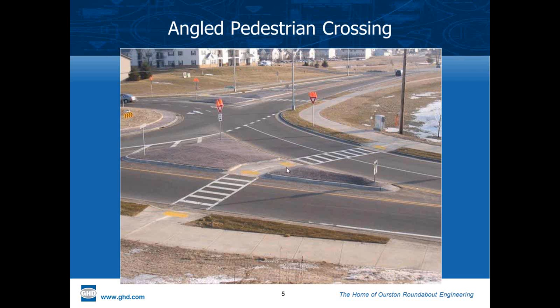In some instances, the exits will place the crosswalk sometimes two vehicles back because we don't want traffic to queue into the roundabout. But on entries, we tend not to push it too far back. Otherwise, we make distances walking around roundabouts too long and circuitous. And then pedestrians, you know, will ignore those crossing accommodations and cross where they please, the shortest path. And that's particularly important with roundabouts in frost climates or cold climates, if we want to minimize